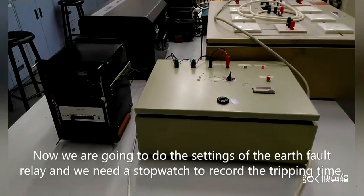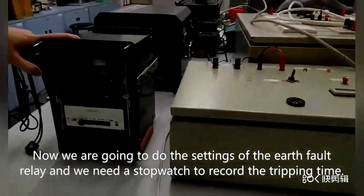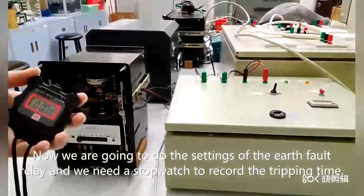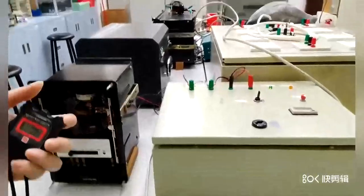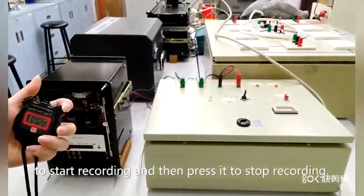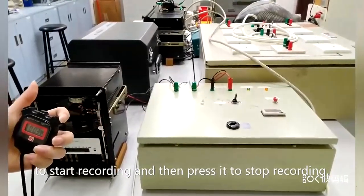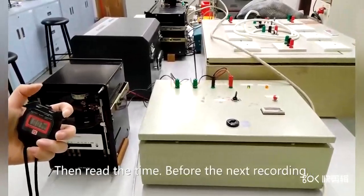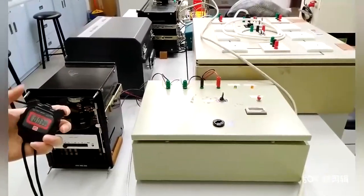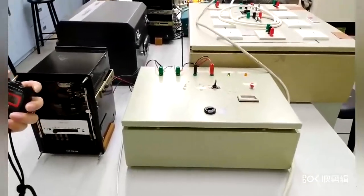For the settings of the Earth fault relay, we also need the Earth fault relay, and then we need a stopwatch to record the tripping time. Press the right button to start recording time, and then press it to stop recording. Then read the time. Before the next timekeeping, press the left button to reset.